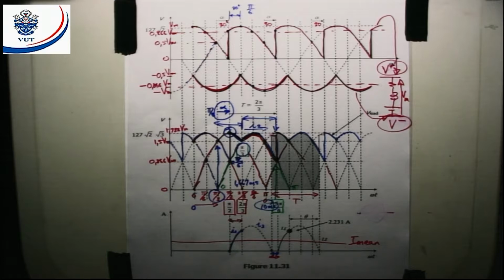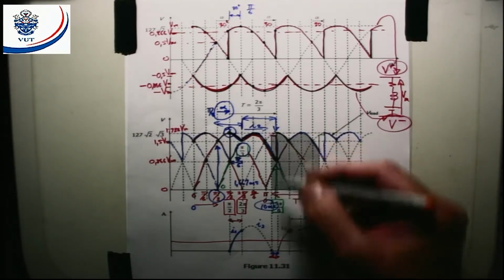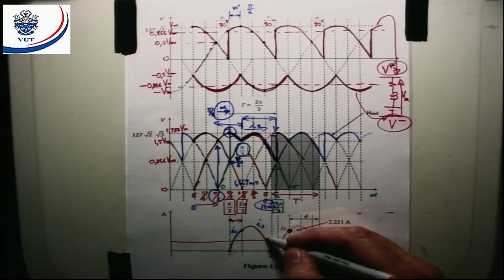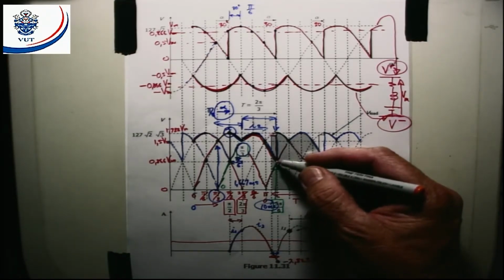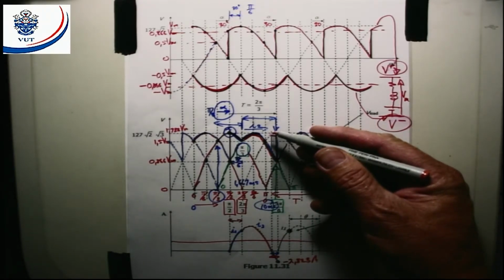Did I answer you? Okay. Now, I want to find out, what is this current? This current I2 of mine, is it positive, 0, or negative? So I find out that it is minus 2,823 amps at the point where I would have switched over to the next line voltage. Now if it's negative, then it means it has gone through 0 previously.